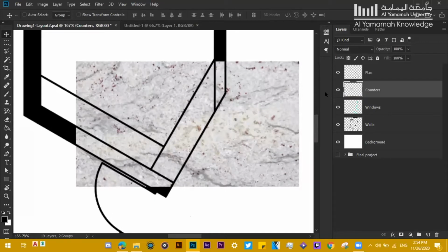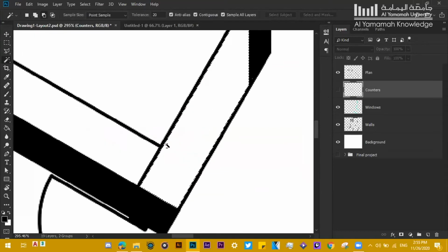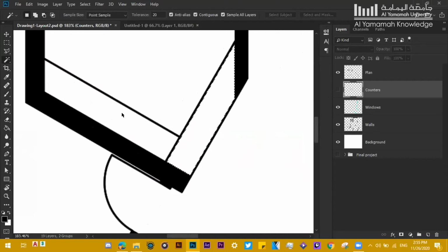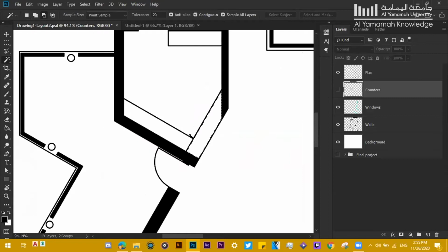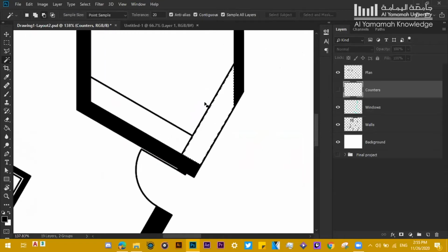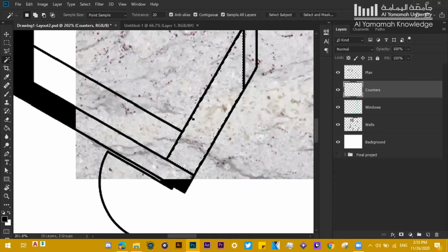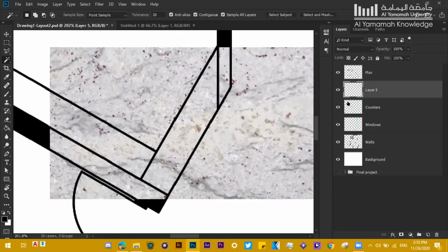You have to hide the layer. That's the first. Go to your magic wand tool, select the countertop. Now when you select this countertop, you don't have to do the modify and select thing. That's just for the walls and for solid color places. This time you could just select and then go to your layer that you wanna, the material, and just unhide it. Now you have to press this command. It's Control J. This is easier. J as in John, not J as in George.